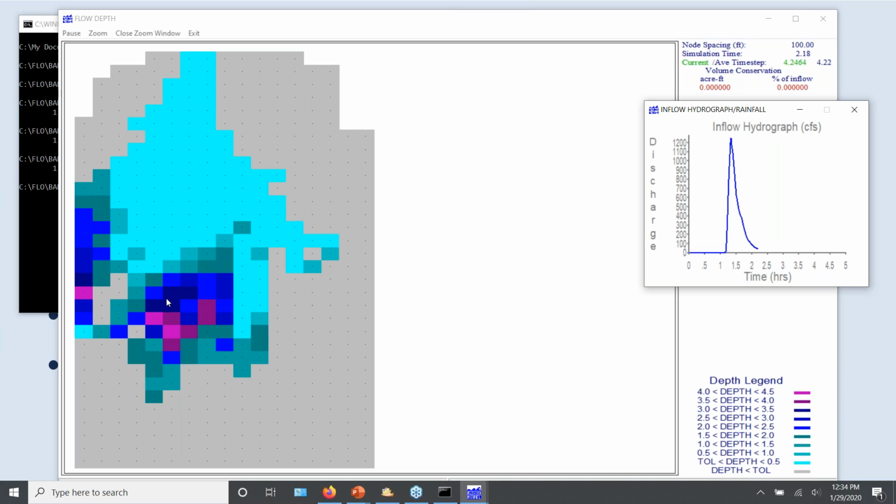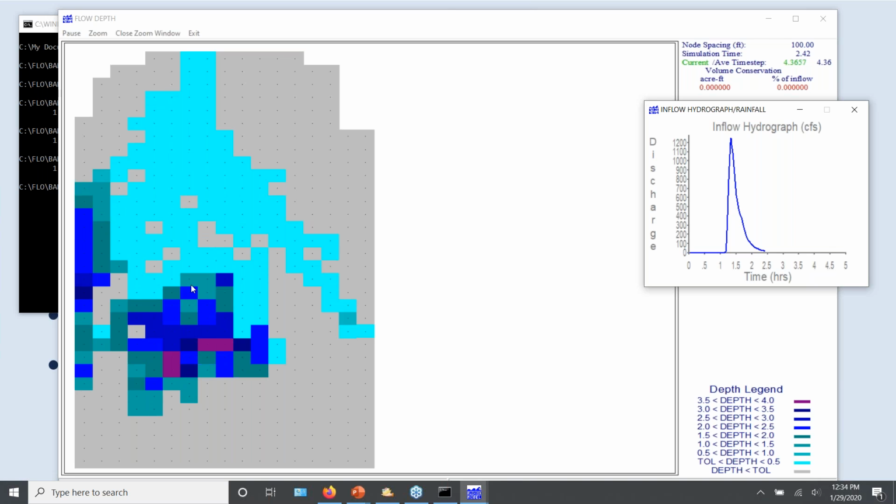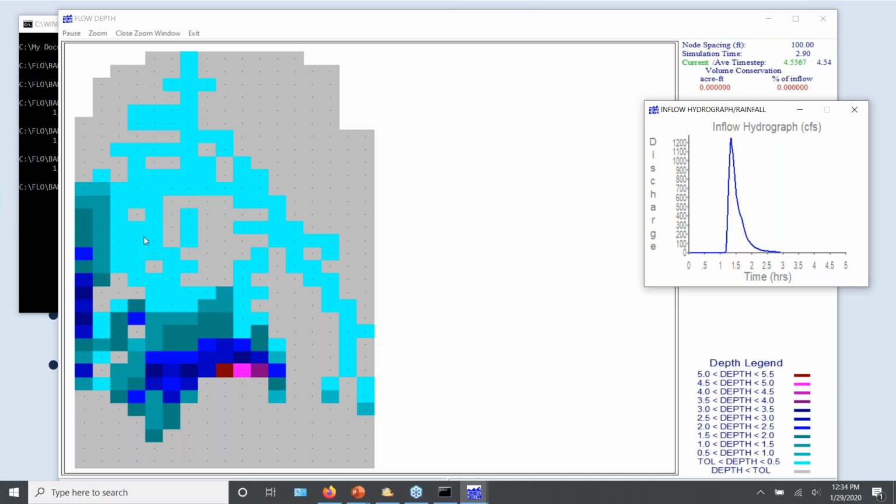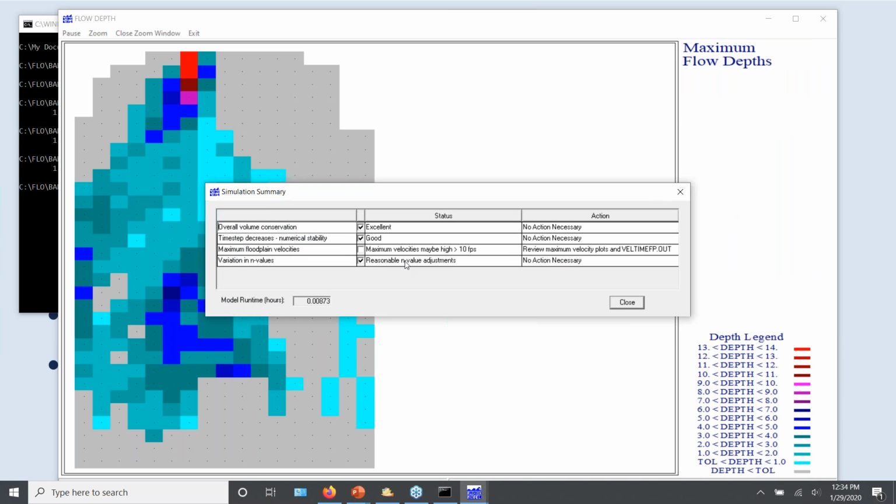But here what you see is that the mud flow frontal wave actually occurred, and the peak of discharge. I took the streets out, ran the mud flow model again, and you saw the peak come down, get onto the alluvial fan, and without the streets conveying the flow down to the terminus of the fan, the mud flow essentially stopped. It didn't even make it to the end of the model simulation. And this is somewhere in the area of that decrease in the steepness of the slope, that it ran out of steam and essentially stopped moving.